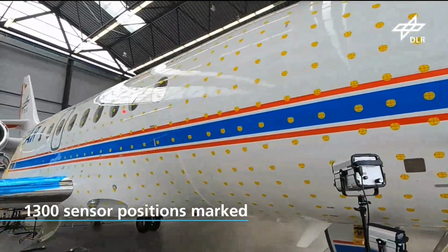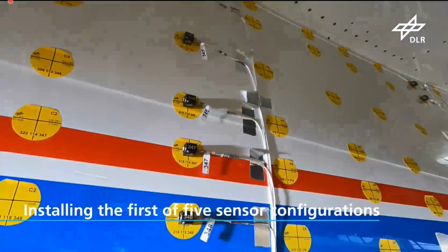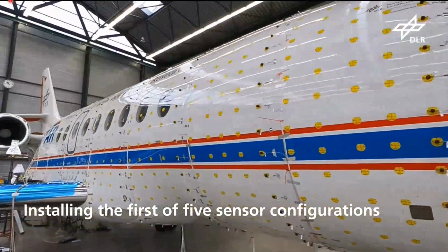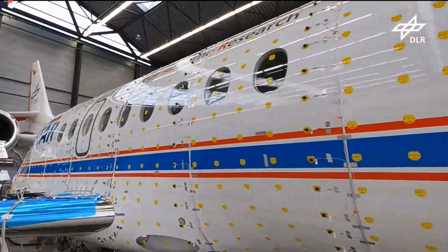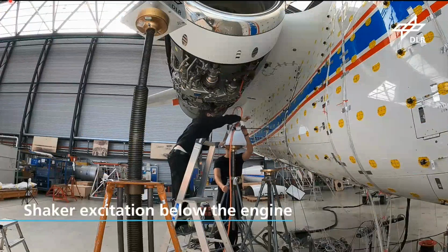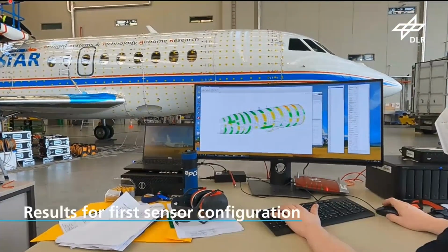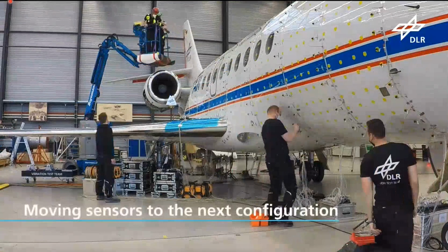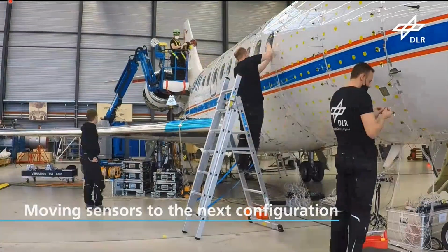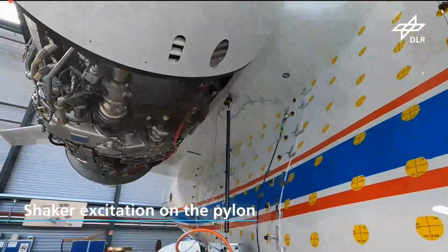After marking every sensor position, we installed the first configuration of sensors and performed the excitations with the shaker on the 4 locations I showed you earlier. Here you can see first results, and after every excitation round we pushed the sensors 1 step back towards the tail of the aircraft and performed the same excitations with the shaker again.